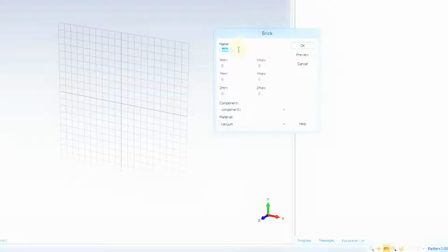So this little block that I've just clicked here is called brick, that generates a sort of six-sided 3D figure, cube or a rectangle, analogous. And you can either pick points with your mouse, or you can press escape, which I'm going to do, and that brings up a little text box or message box into which you can type things, which will help in making our project a little bit more easy to maintain and modify afterwards.